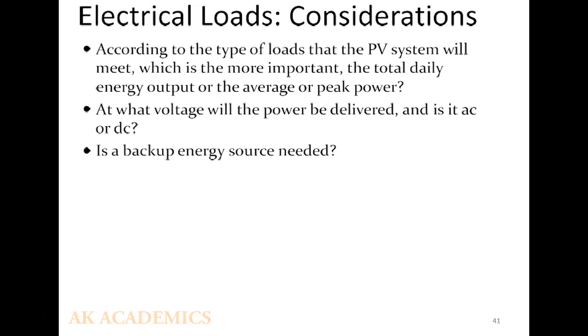Okay, the next question you want to ask when considering the electrical loads of PV systems during the design or installation is: is there going to be a need for a backup energy source? That simply means when the PV is not working, do we need a backup energy source, either like a wind source or a generator or a grid or other kinds of sources, so that when the PV is not working, there is something else that would supply power. This is to ensure that at any point in time, there is no lack of supply of energy to the load that should be met.